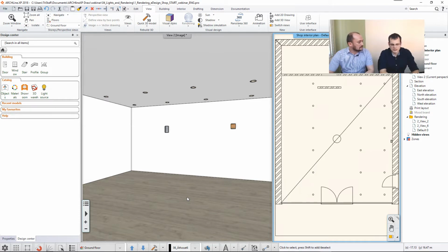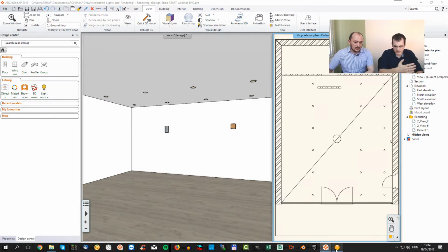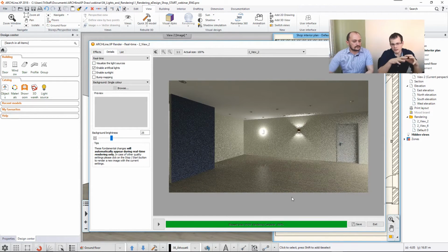There's one interesting thing I learned while learning how the rendering engine works and what's the rationale behind it. When you're doing a rendering and you look at a certain space within your 3D model, even if there are things which are behind you, outside of the rendering boundaries, they are also going to be rendered. The software needs to make sure that those things which you can see have any kind of effect on what you actually see. So in order to avoid those things being calculated needlessly, you can put them on another layer and disable them. That's one thing that you taught me in the beginning.